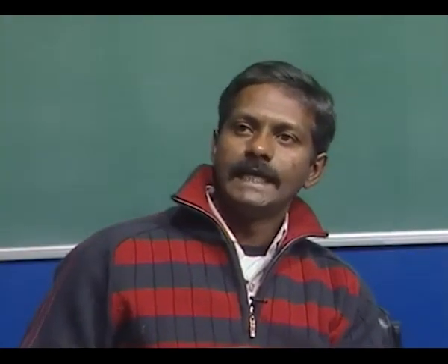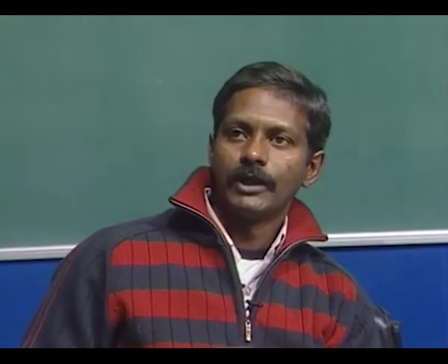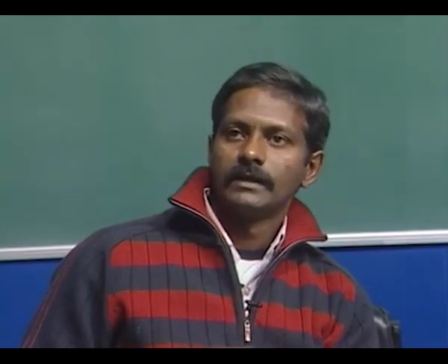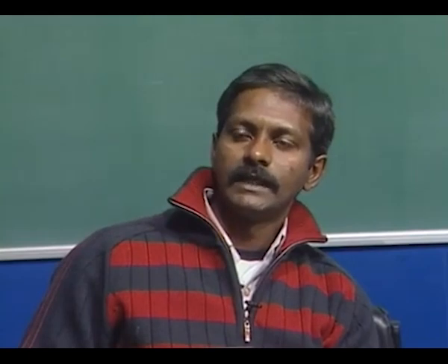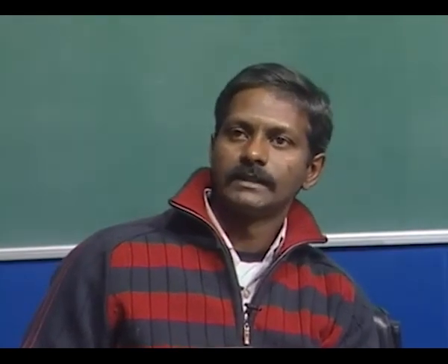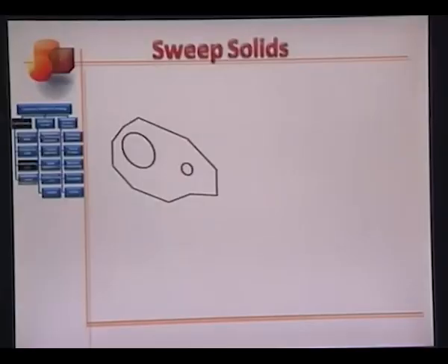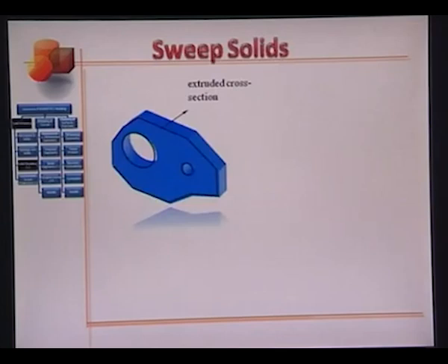There are other techniques that different solid modelers tend to use to generate primitives. They are essentially categorized or classified as sweep operations. One can come up with a cross section something like this, with outer and maybe a few inner loops, and one can think of extruding this entire cross section in the third dimension to get a primitive like this. This is called the linear sweep operation.